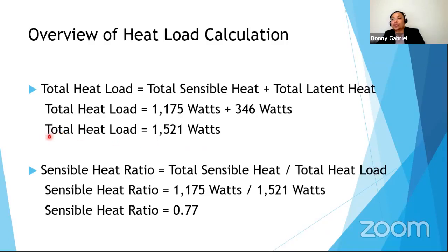Okay? When you select an equipment, for example, bumili kayo ng aircon, no? Yung split type. Nakalagay doon, kailangan ito, ang kaya nito is 2 horsepower or whatever kilowatt or whatever watt it may be, sabi niya. But you have to check yung sensible heat ratio or yung sensible load na kaya niya lang. It may be 1.5 pero ang sensible nila pala is 1,000 or 1 kilowatt. The 500 watts would be latent. Yari ka pa din. Undersize ka pa din.